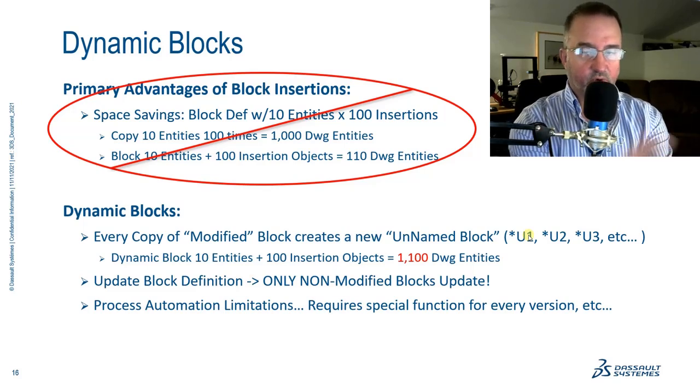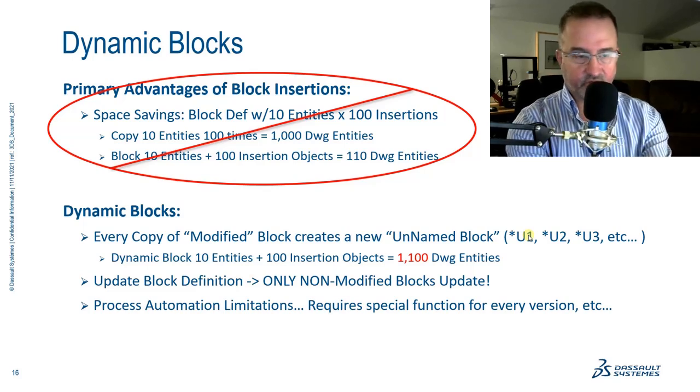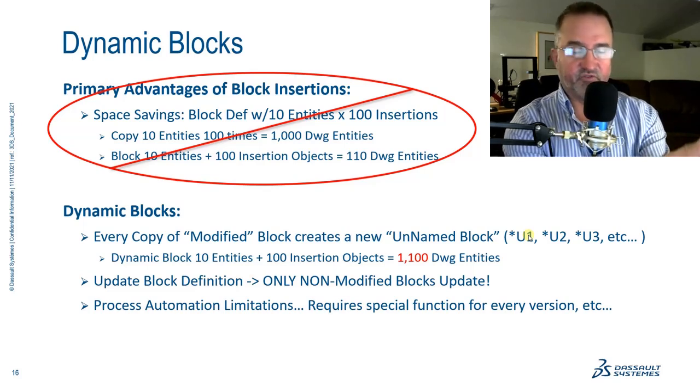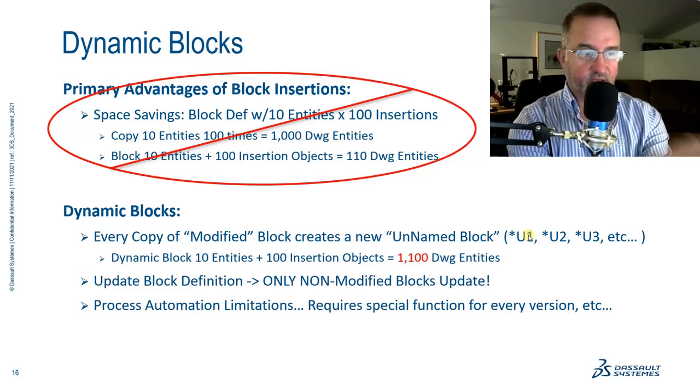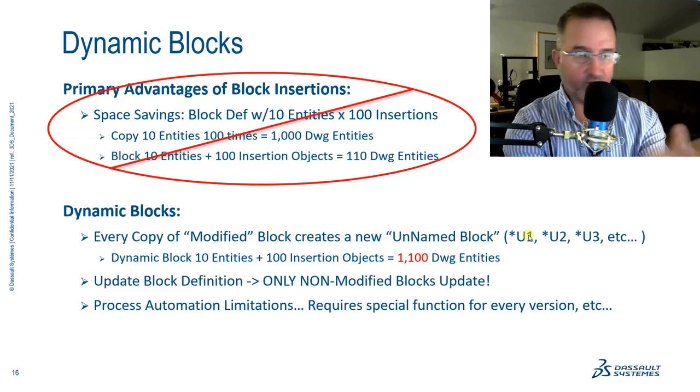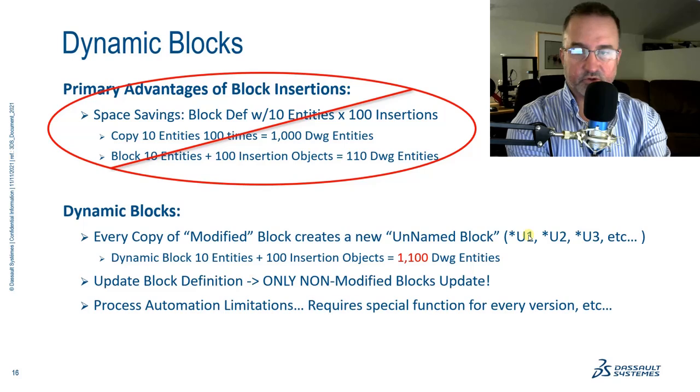I do an example where I give you a title block and I can export the information through multiple different means just to get it out to an external file. Now, it takes about 4 or 5 lines of code in Lisp to make that happen. It's very simple, very easy process. I can grab all the entities in the drawing, check to see if it's a certain block. I can extract them either through an extraction table, the attribute extraction method, or I can use Lisp to find different ways to do that.